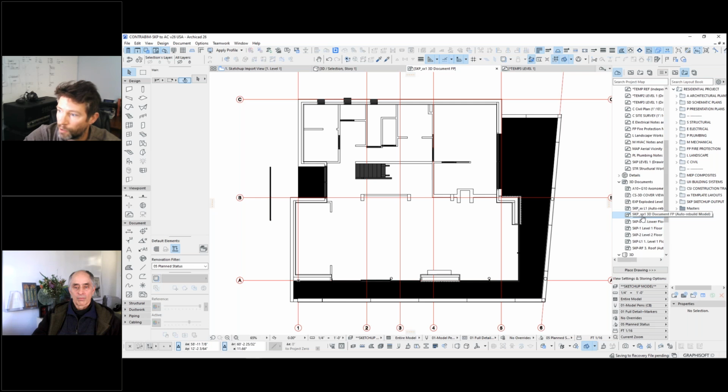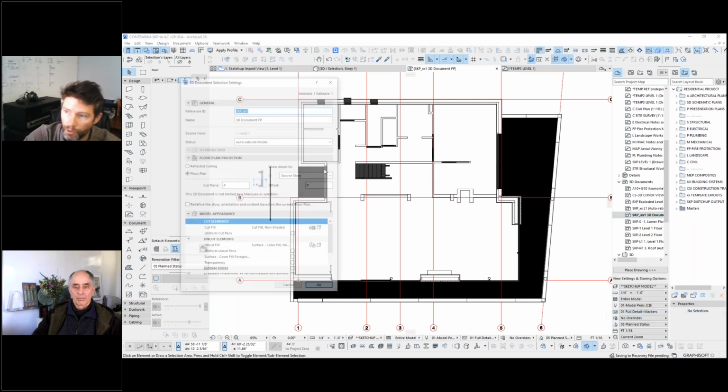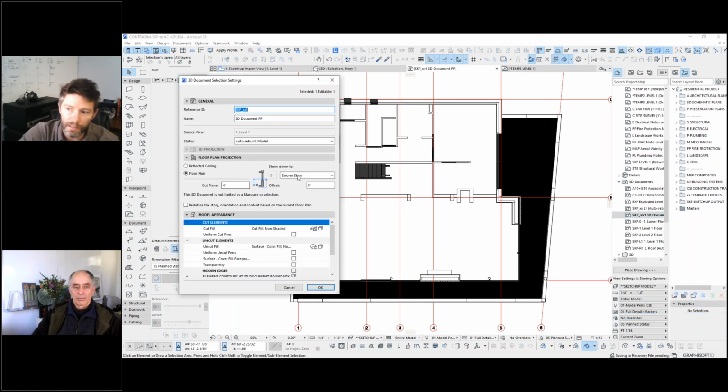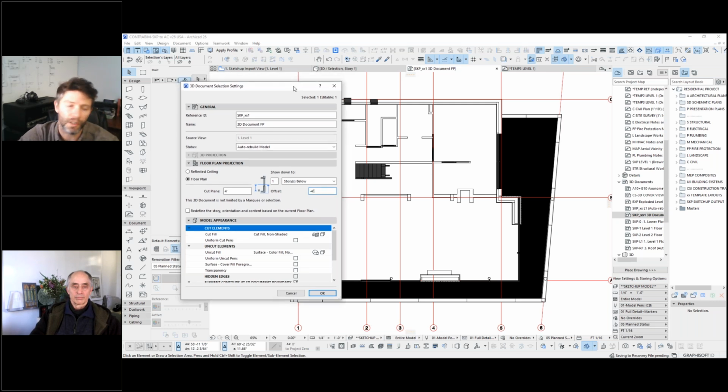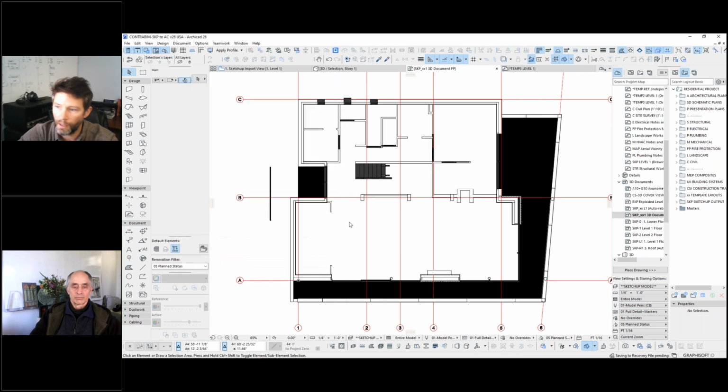Going from this 3D document, let's just, for example, say we wanted to see down to 1 story below, and we set an offset down. I can never remember if it's a positive or a negative direction here, but let's go down like -4 feet, I want to say, for the purpose of trying to pick up the walls from down below. So let's turn that on, and I may have to go turn on my hidden lines. Let's see.